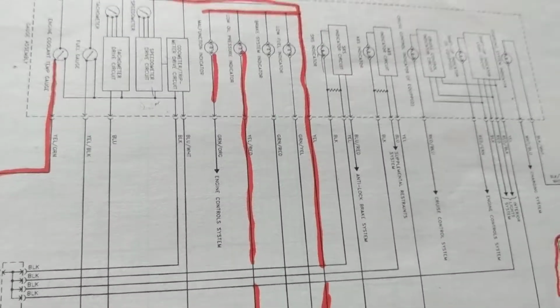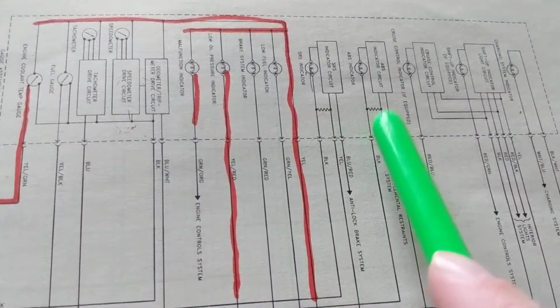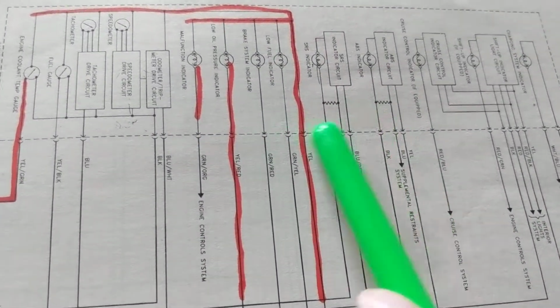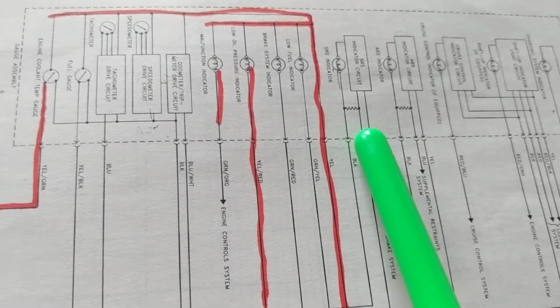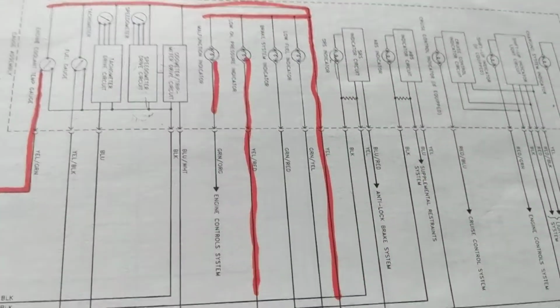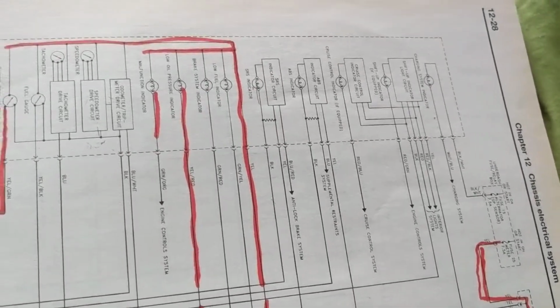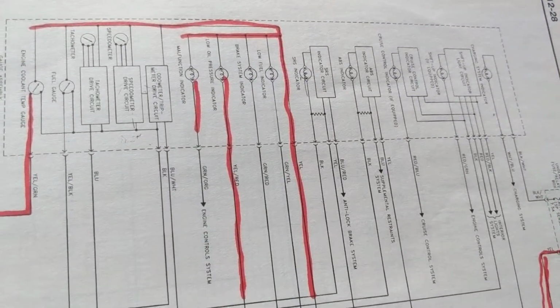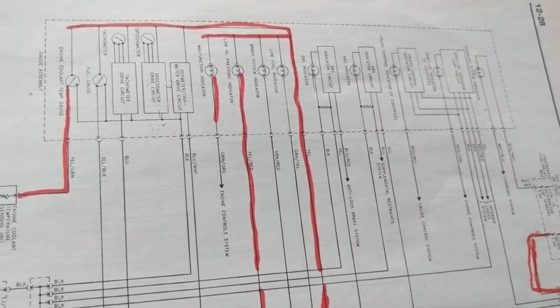So, if you have no lights, again, in the instrument panel, in the dashboard, right? You probably don't even have 11 volts. You probably have like 10.6 volts. The lights don't even come on. Forget it. That's about 12 amps. You can't even crank 12 amps. Don't think about cranking 200 amps or whatever you need. All right? One more to go over.